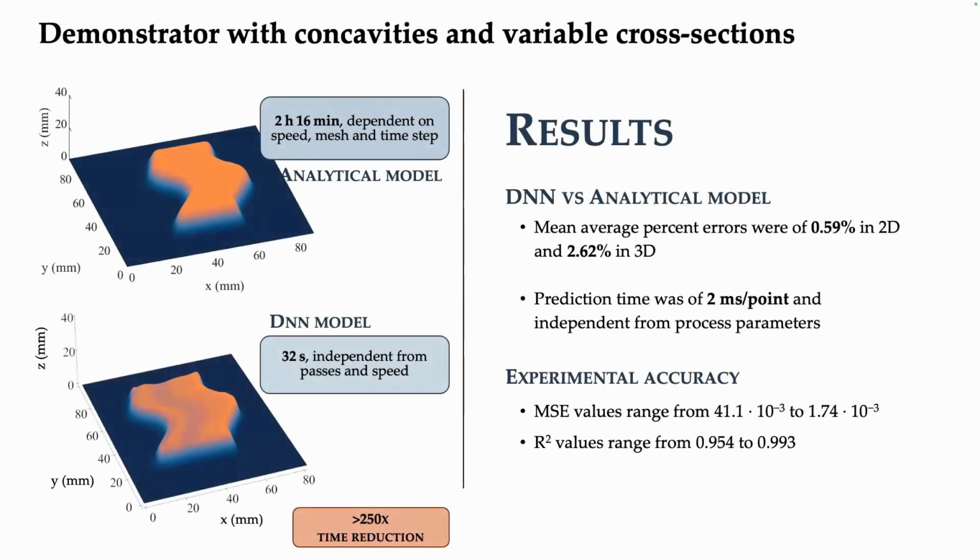I'm showing you a demonstrator for application of this hybrid approach. The demonstrator has concavities in order to validate the robustness of the scanning strategy designer. And it also has a variable cross-section to validate the effect of the adaptive slicing approach.